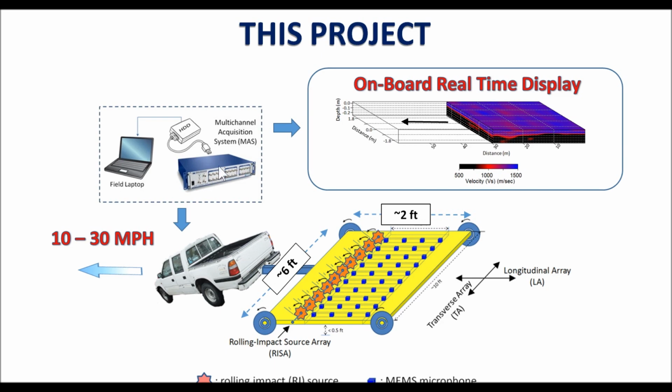And onboard hardware components of A to D conversion and real-time acquisition will collect seismic data in real-time mode and feed it into the onboard laptop computer that will be analyzing incoming data in pseudo real-time mode and display the results in 3D format similar to the one displayed here, so that we can see the actual variation of shear wave velocities within the HMA layer and also its thickness variation as well.